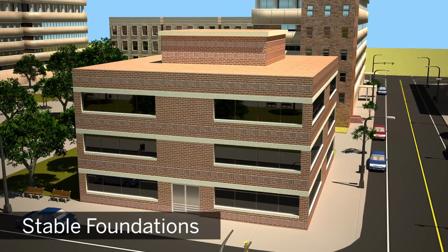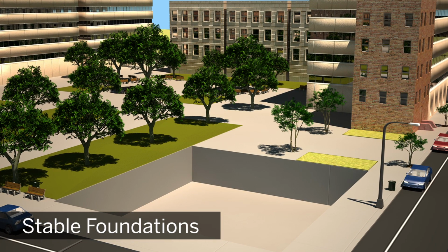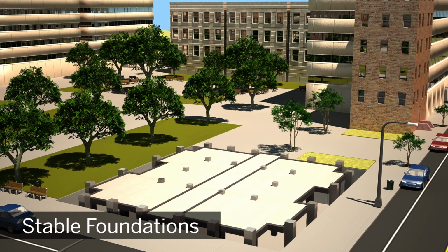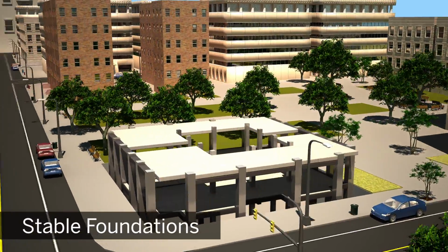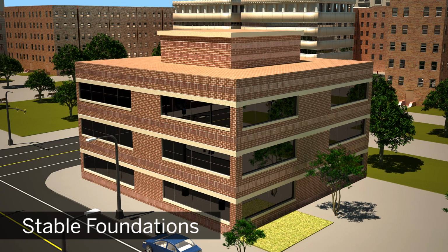In addition to being able to support a structure's weight without excessive settlement, the foundation system must be able to resist earthquake-induced overturning forces and be capable of transferring large lateral forces between the structure and the ground. Foundation systems also must be capable of resisting earthquake-generated ground deformations without causing large movements in the supported structures.